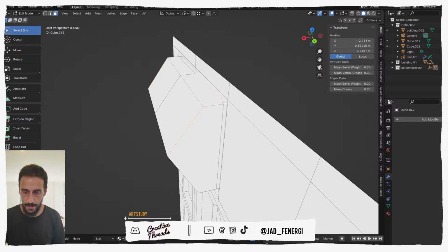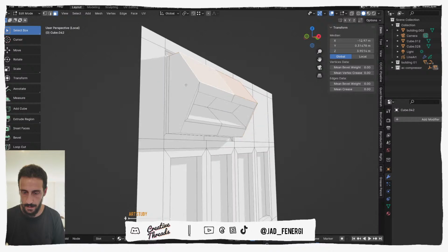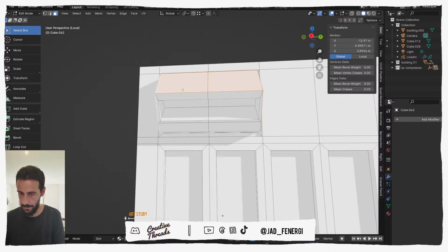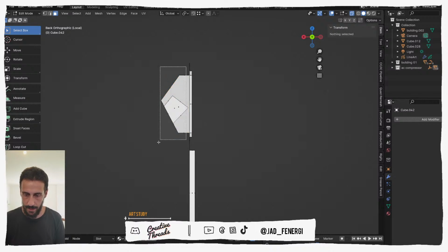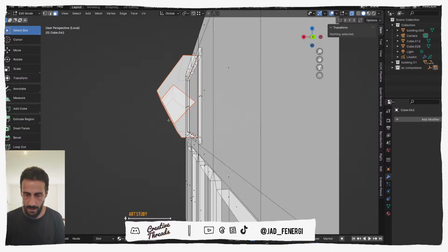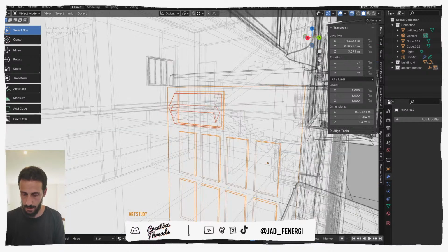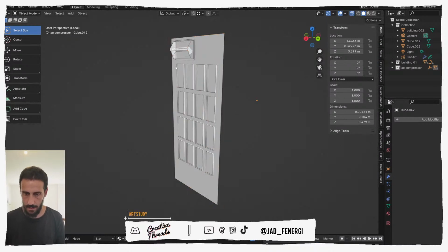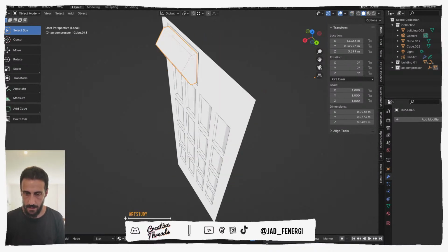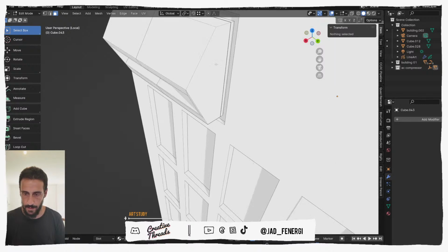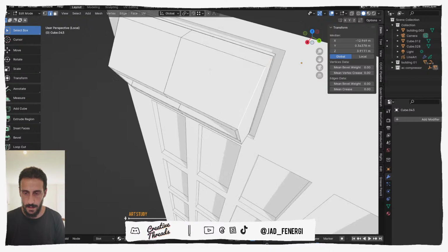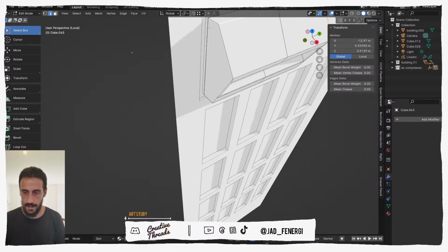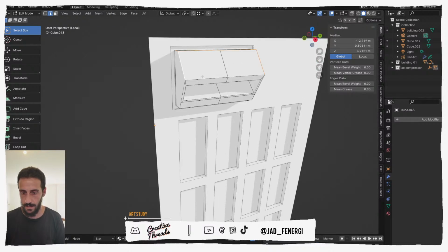You know what? Let's separate this thing. Let's go to the left view. Alt-Z. Let's separate the whole thing. P, selection. But since that's a separate object now, let's pick these edges, actually, not faces.